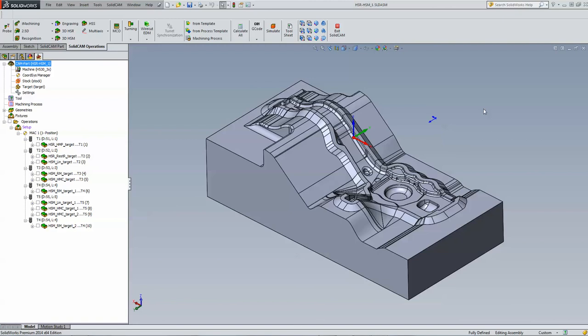Okay, now again, I started off, and this is the way we actually did this. This is a mold, and we've done roughing operations over here, and what we call semi-finish operations, stage 1, semi-finish stage 2, and then finish operations on the part itself.